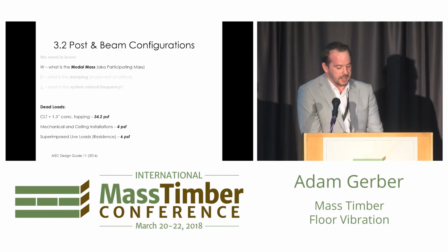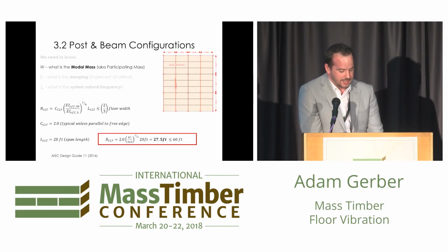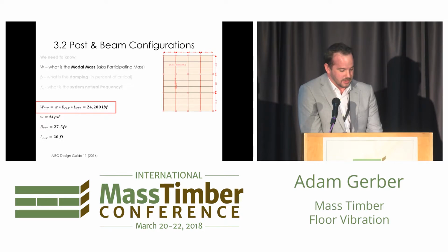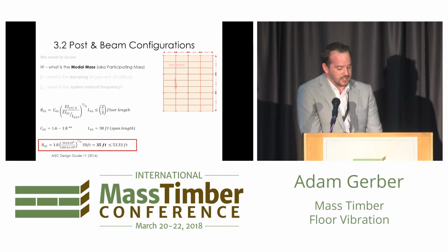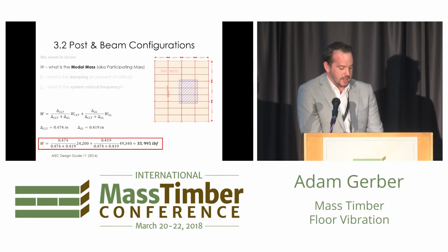So we can go through and we can calculate pretty easily what's the self-weight of the system, adding in the additional dead load. And I'm not going to spend any time on these. They're in there just for completeness. But we can calculate the effective weight of CLT and the effective supported weight of a single glue-lam girder. And then we can combine them and get a total supported mass that's going to be activated by walking.